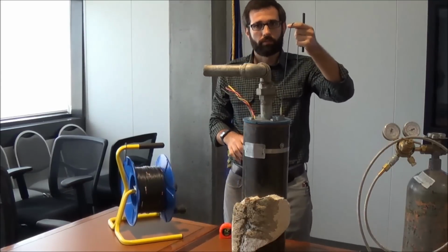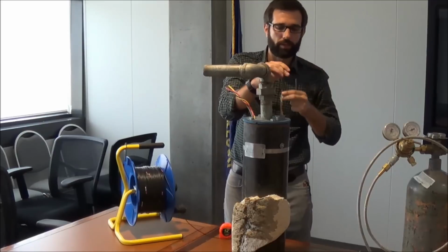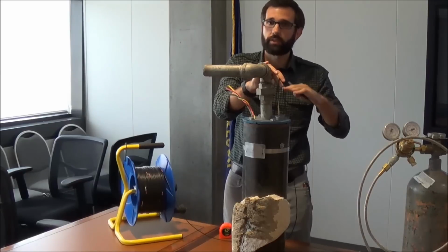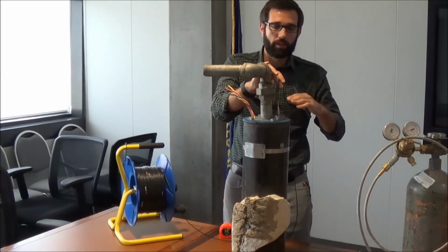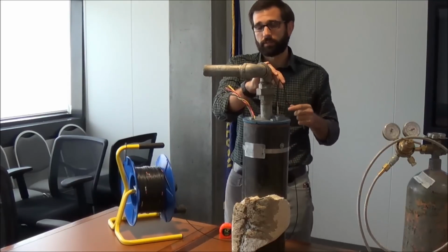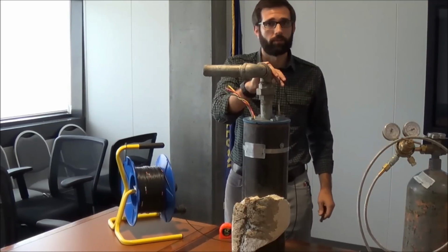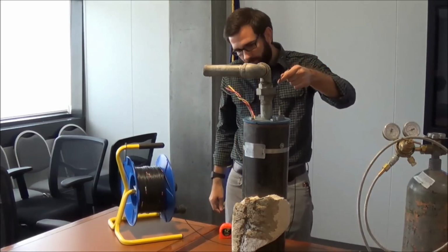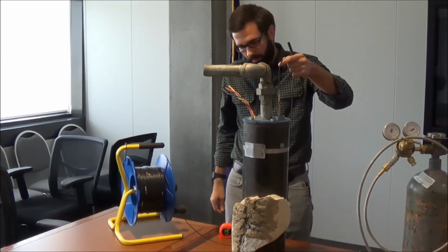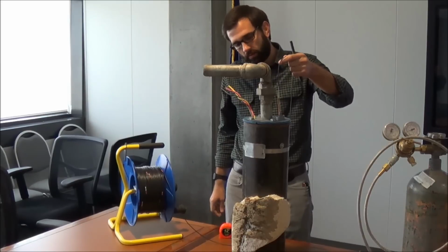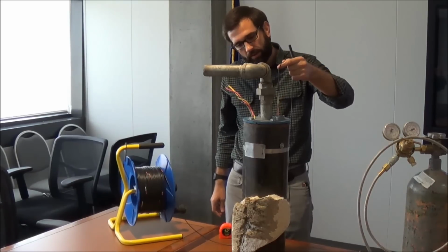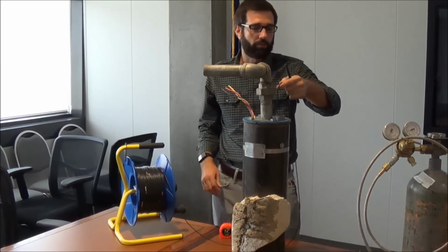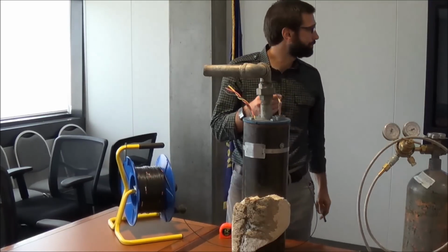You've got to make sure that you're monitoring the line weight. Make sure you always have weight on the line. If you lose weight, you know that you're probably stuck, you're sitting on something, and you shouldn't put out any more line because it has a better opportunity to get tangled up in the well. If you do feel something, just shake it. You can feel that the weights are moving freely. If you're stuck on something, they won't move back and forth as easily. You'll know that you've got an issue.